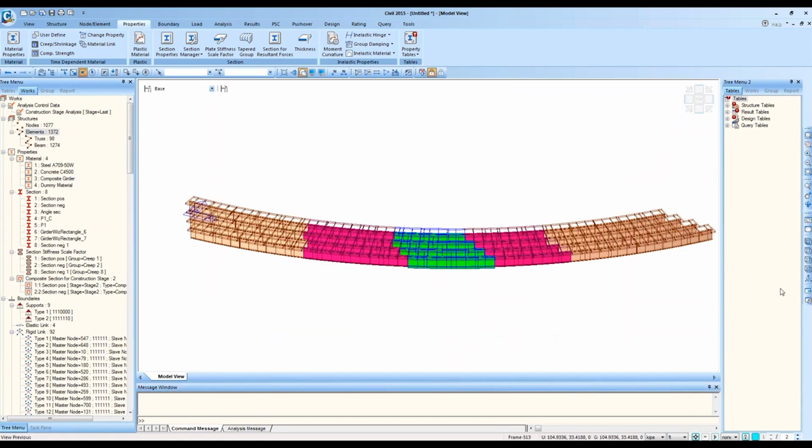So if you're working on a preliminary design project, let's say you only start with one approximate girder section and concrete deck, you can always come back and easily modify, run the design and do the design check. And based on the design check summary table, you'll be able to easily figure out how to modify your girder or the concrete portions.